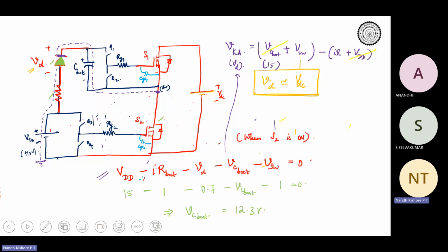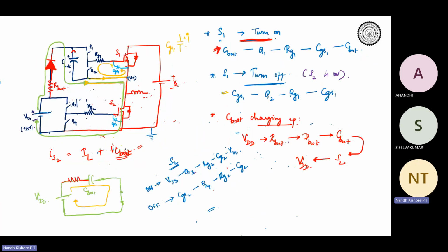Okay, so we were telling that we do not need multiple gate drive supplies, we do not need isolation and all, right? But one drawback is that the diode that you use should be rated to the DC bus voltage and that can increase the costs. Okay, but comparatively, people have seen that this is much cheaper than the conventional approach we had seen earlier.